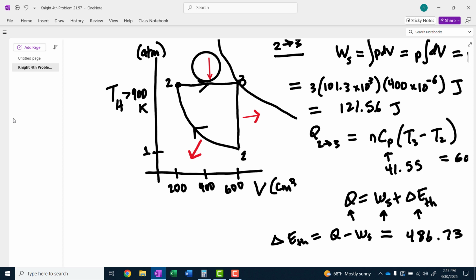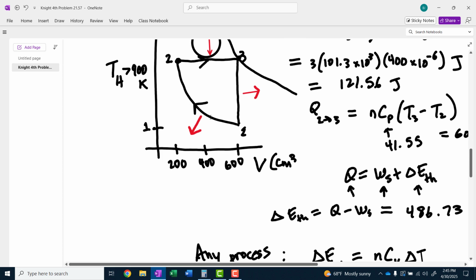And it's a little murky sometimes, what really is the hot reservoir, because for the case of the internal combustion engine, the high temperature reservoir really would be the combustion products after you ignite the gasoline, but that's in the same physical space as the gas. The gas is in the cylinders, and so is the hot combustion products. So it's a little weird to separate the gas from the reservoir because they occupy the same space. Your book doesn't really address that. I don't know how to make that less murky, but let's also look at the other two processes.